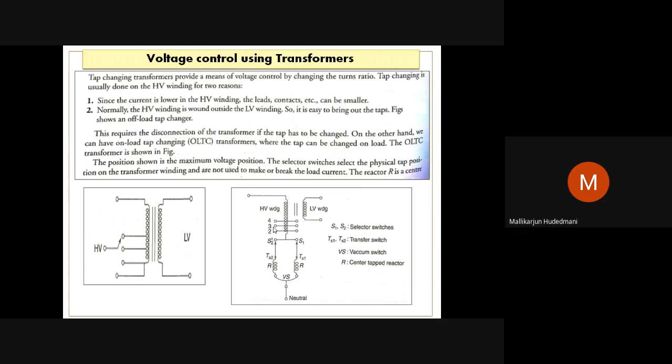So this is the provision made at the tap changer of a transformer. This is the logical way of switching. If I use this mechanical kind of switching, you are very sure that I have only one contact getting engaged with either of the points, either point 4, 3 or 2. I am engaged here with only one point. Therefore, we have to take care. There is discontinuity. When I move the contact to the next one, there is a momentary break in the service.